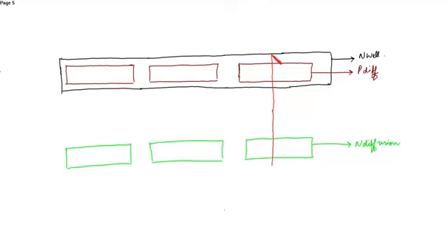In the inverter, first you have to draw the gate so that we can apply the input. So the input to the gate is S, and the output will be obtained from the combination of the drain of the PMOS and NMOS. This is the source, drain, source and drain.